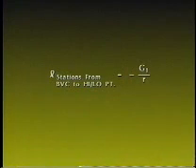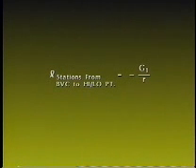At the high or low point, the slope of the tangent to the curve equals 0. Therefore, the value of little l, the stations from the BVC to the high or low point, is equal to G1 divided by the rate of change. Changing the sign of this value will always yield a positive number. This provides a good check that all the algebraic signs have been carried correctly.